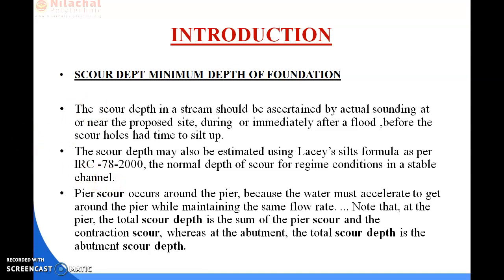Basically the purposes of the foundation are to distribute the load of a bridge over a large bearing area and provide stability of the bridge against settlement and tilting. It is provided sufficiently deep so that it is not affected by the scouring. So next come to discuss about your scouring. Scour depth. So what is scour depth?